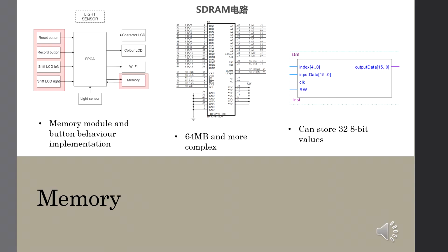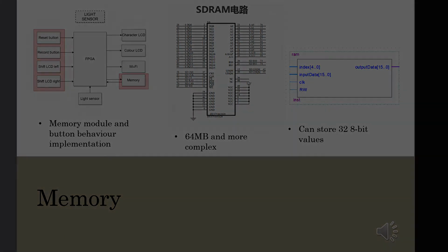To keep track of how many readings there are, a register called global address is used to point to the next available address. Another register called selected address is controlled by the navigation buttons to change what data is to be cleared or outputted to the display.